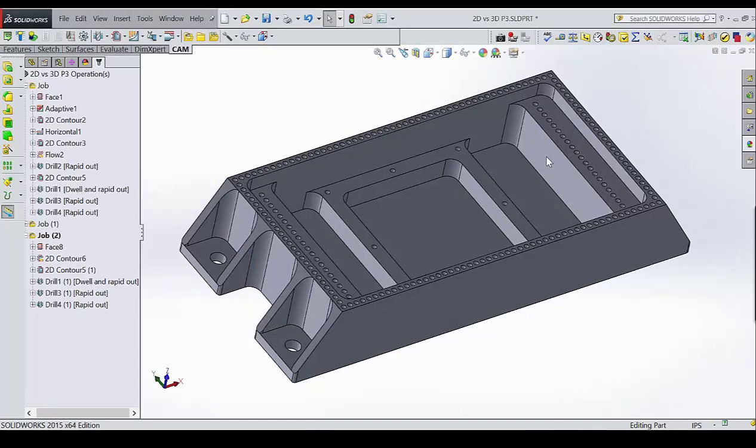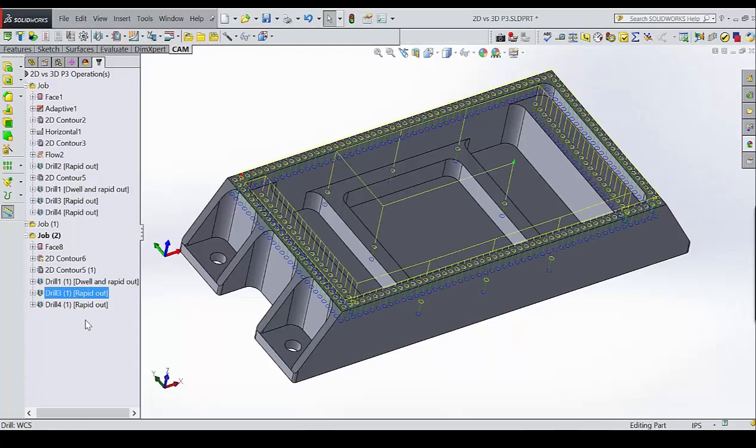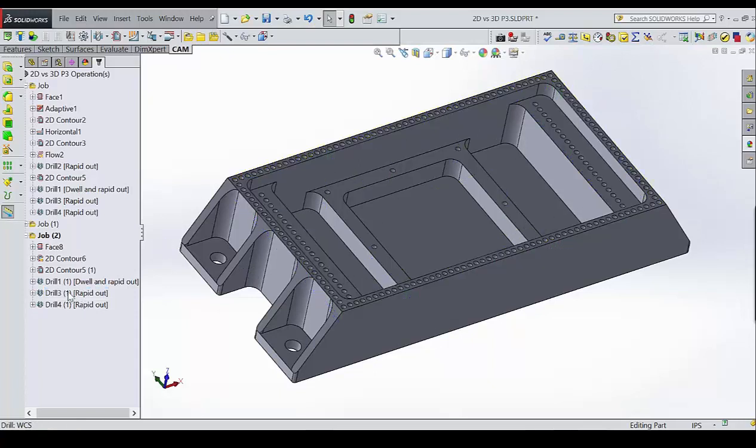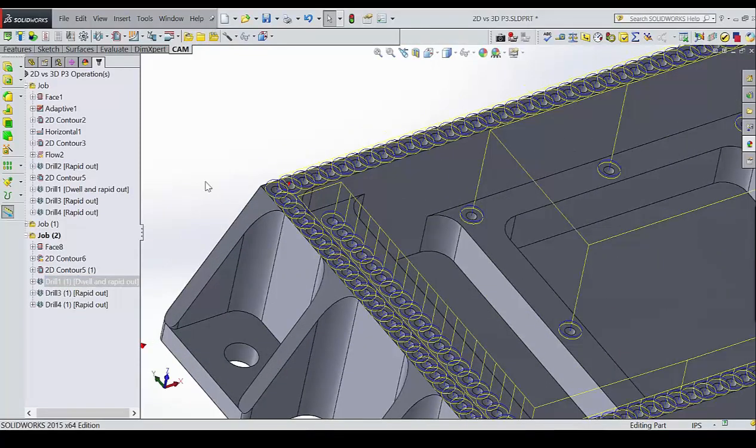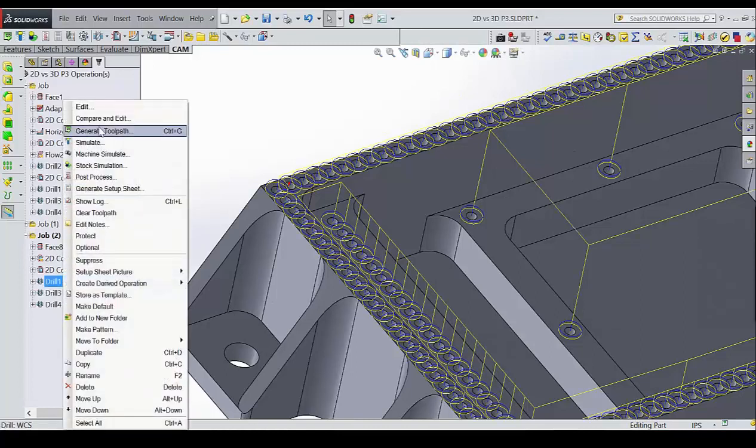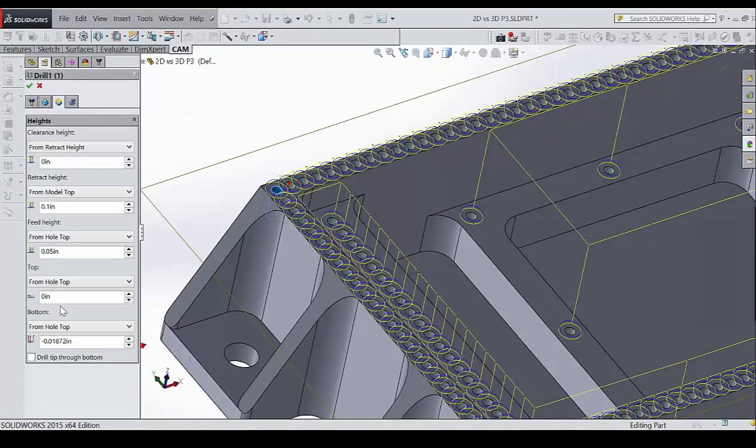How are you programming the template to drill the different depths? Oh, let me show you that. This is where in other software I've used, it's something you just kind of slog through every time, or maybe you have a bunch of notes on your corkboard or whatnot. I did go over how we made the chamfer diameter or the spot drill diameter, so I'll pass on that. Just to kind of overview it, the way I defined the top and the bottom was from the hole top, and I went negative from there. But that's the calculation that I just showed you.